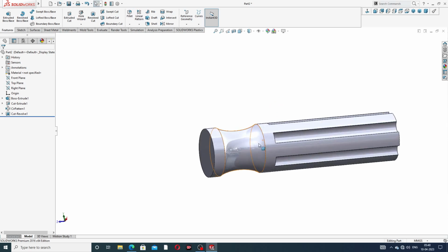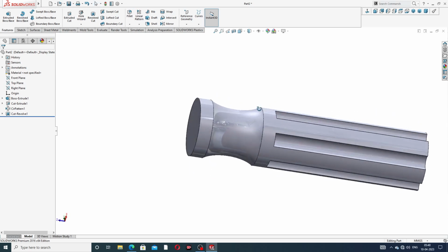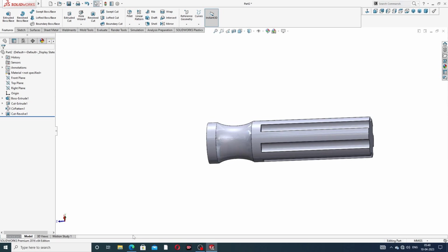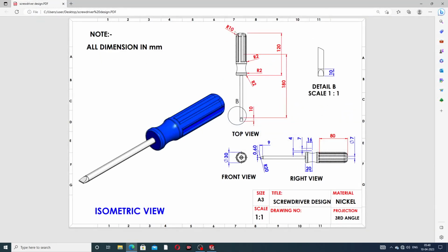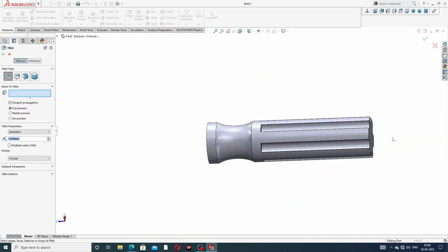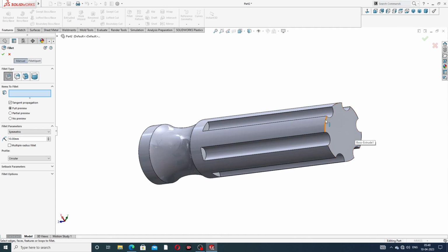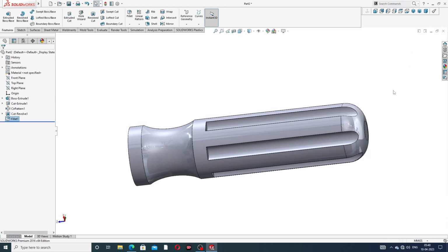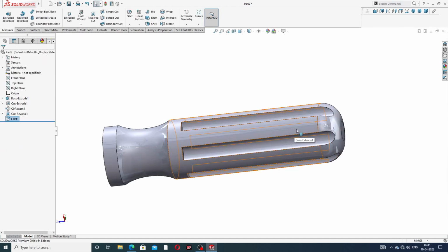This cutout is very nice. Next point, use the fillet here, 10 millimeter, and 2 millimeter on all sides. At first the big fillet is used, 10 millimeter, and click any edge, select here, and this is perfect, and click OK. This is looking perfect.